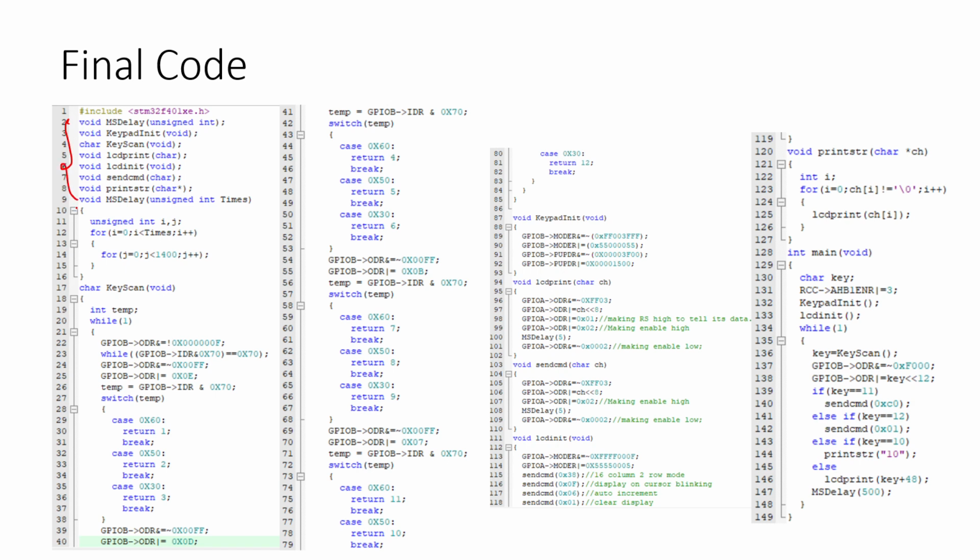First you will initialize all the functions, that is, you'll declare the prototypes and then define all the functions starting from ms delay, and then you'll start with key scan. Once the key scan is done, you will have the keypad, wherein you'll have keypad specific MODER register and PUPDR register configurations. And after that you'll have LCD drivers, and in the LCD drivers you will also have LCD init, which will take care of initializing the LCD.